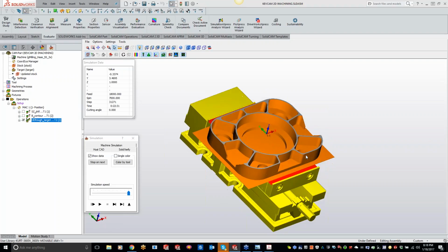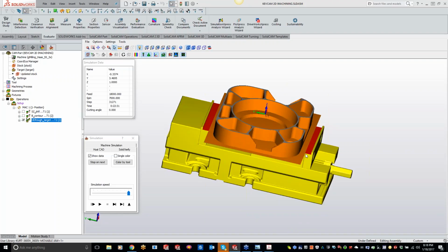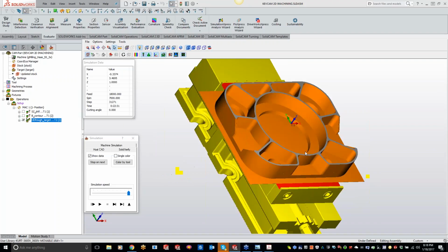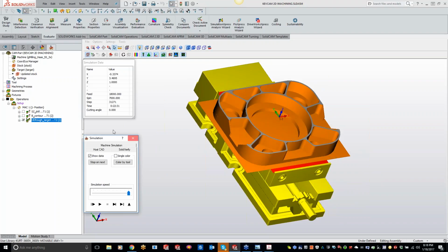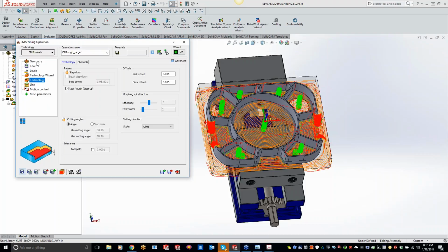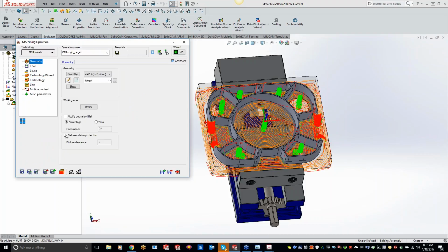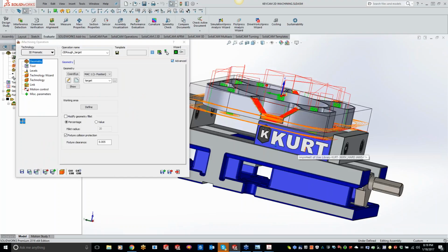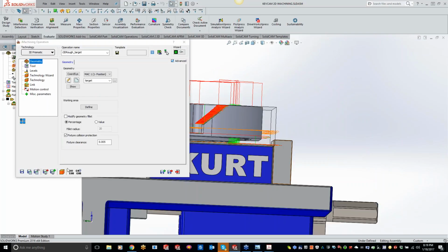But now you'll see that I actually just wiped out my vise, which I forgot to turn on for you guys. So what I'm going to do now is, with our new feature that we have added under the geometry page, turn on my fixture collision, and I'm just going to do a clearance of 5 thou, not 2 thou, 5 thou. Now you'll see my toolpath, let me get this rotated around here, is currently going through my vise. So now if I do save and calculate,